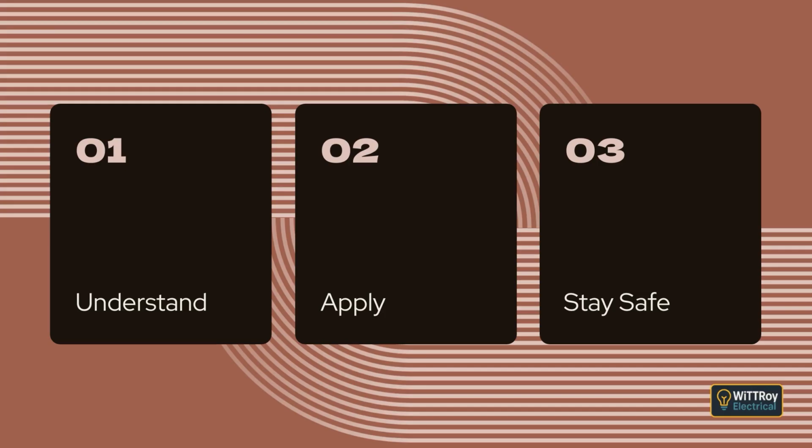This means if a fault happens on one circuit, only that affected circuit loses supply. Everything else keeps running normally. The protective devices should be selected so they do not trip too easily, and should also be adjusted to work in the right order. The standard also reminds us that the settings of these devices must be checked during inspection. That makes sure the discrimination is correct and the supply stays reliable.